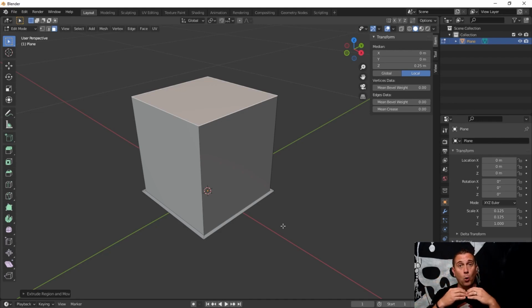So if you have an open mouth shape, you can modify that slightly on one side of the face to get a certain vibe going. And you can do that not by individually rigging them, but by storing different positions and then animating between those positions. In the Babylon world, we call those morph targets. In the Blender world, they're known as shape keys. And to make it even more complicated, in other 3D authoring tools such as Autodesk software, they're known as blend shapes. But they're all interchangeable and they all mean the exact same thing.